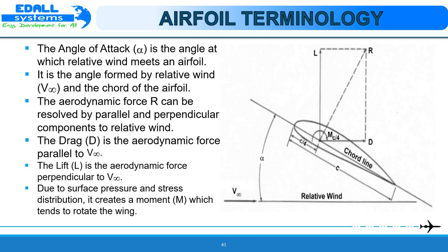Intuition will let us know that the lift, drag and the moments on the wing will change as the angle of attack changes. Variation of these aerodynamic quantities with angle of attack represents some of the most important information that an airplane designer needs to know. We point out that although the moment about the leading edge and the quarter chord point are both functions of alpha, there exists a certain point on the airfoil about which moments essentially do not vary with alpha. This point is called aerodynamic center. The moment about the aerodynamic center is M AC.